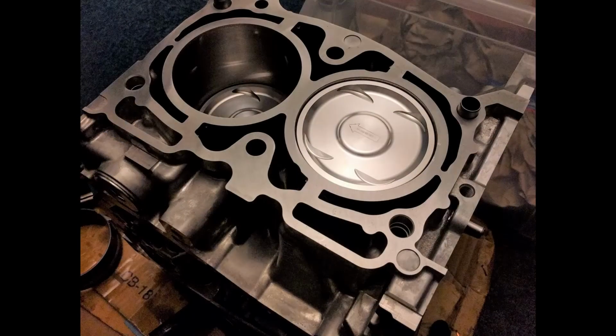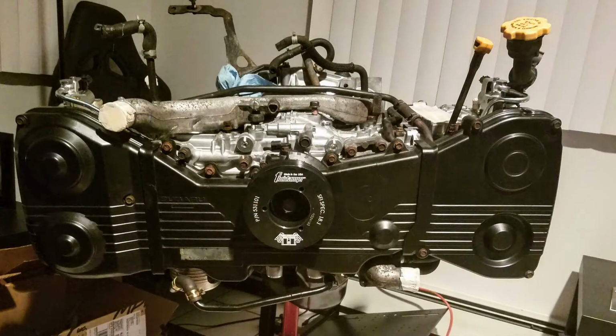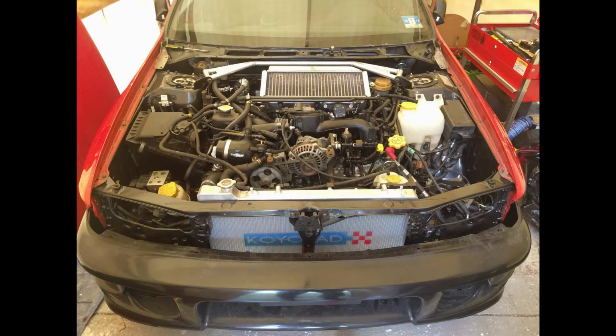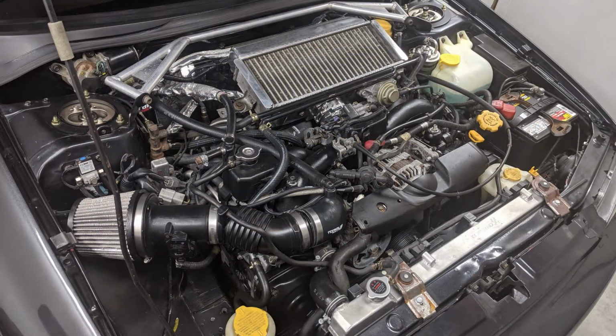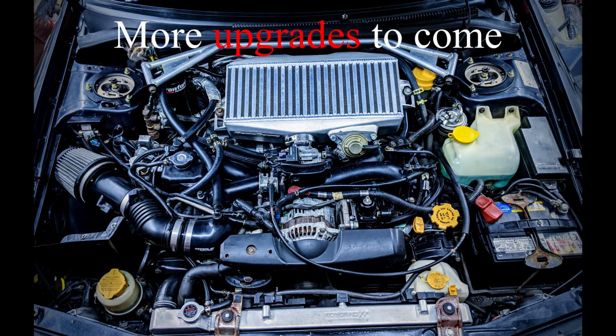You can also upgrade the internals for non-power related gains. Having lighter and tougher rotating assembly usually translates to an engine that can rev faster and can withstand higher RPMs. And this is something that should be considered when building your project. The activity you're involved with and or your driving style may benefit from these changes. So if you plan on increasing your output significantly by adding a turbo, supercharger, or even nitrous, you may want to support that goal by upgrading your engine internals.